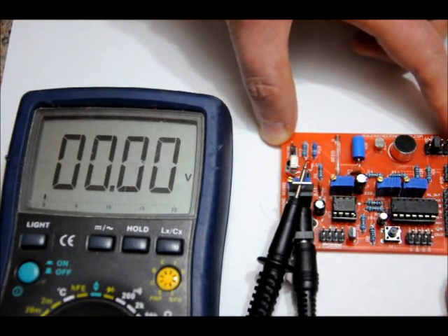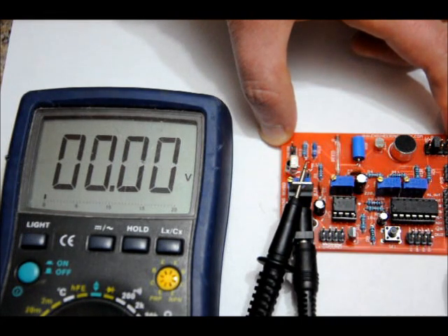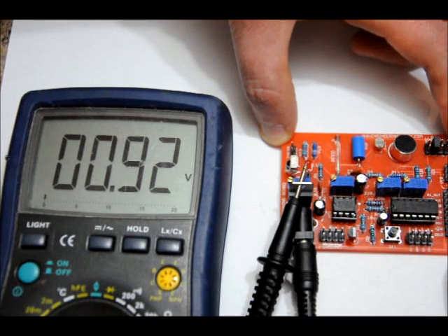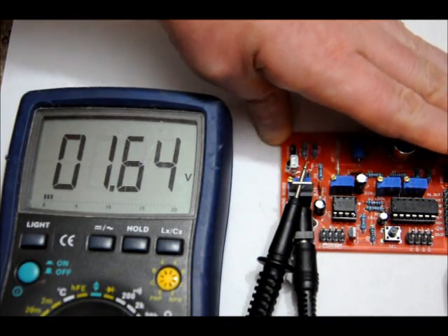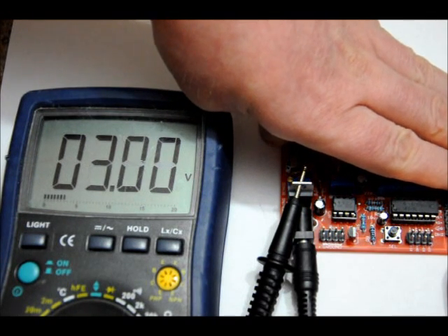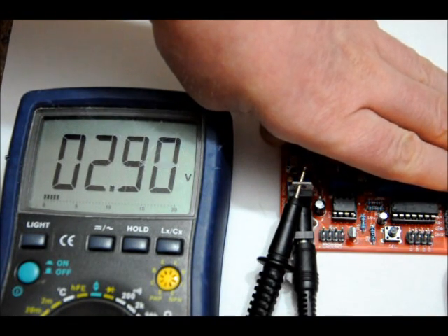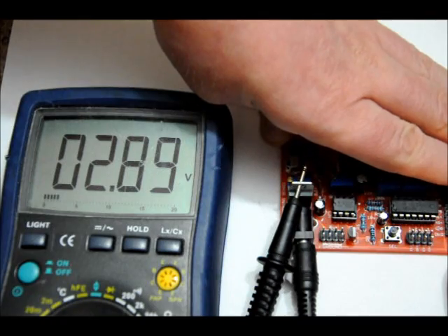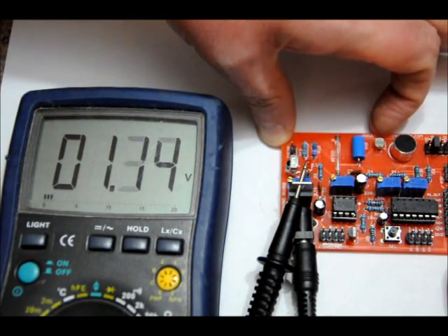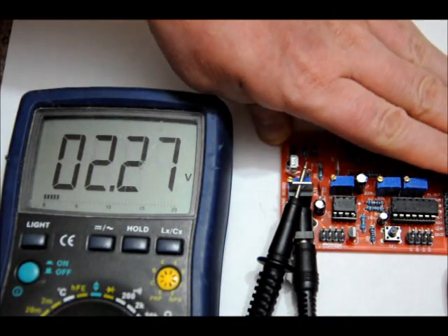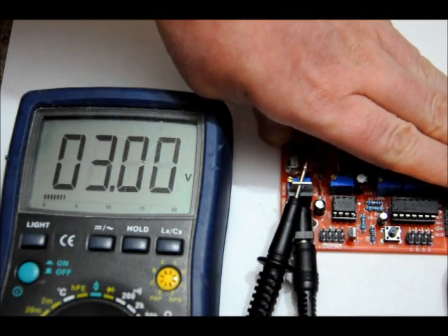Now, in normal lighting, here's the LDR right there. If I look on the div 1 pin, what do I see? 0.92 volts. So there's a fair bit of light hitting the sensor right now. If I put my hand over it, it's not even really all that dark. It goes up to 2.9 volts. So I was off a little bit, but as soon as I turn off the light and there's no light hitting that, it's going to shoot up to more than 4 volts.